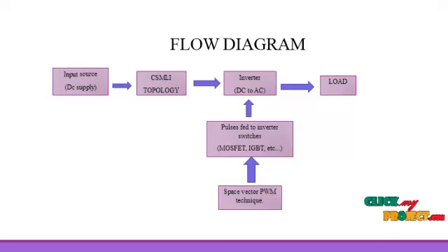The output voltage level of each unit is indicated, and the number of power switches is equal to the number of IGBT power diodes and driver circuits. Another main parameter for calculating the total cost of the inverter is the maximum amount of blocked voltage by the switches. If the values of the blocked voltage by the switches are reduced, the total cost of the inverter decreases, as is obtained using this proposed configuration.